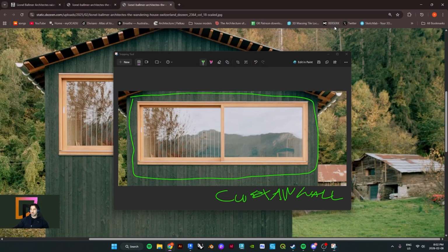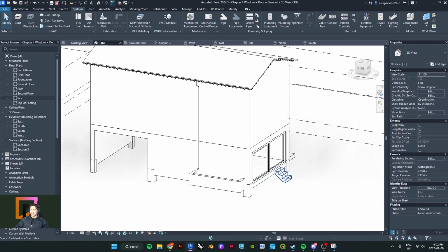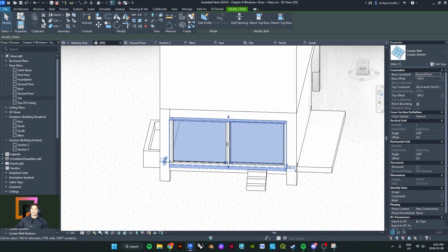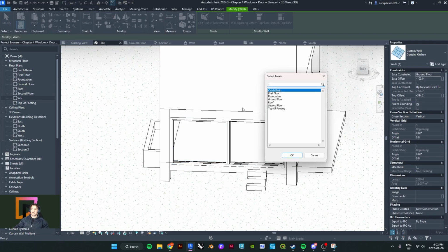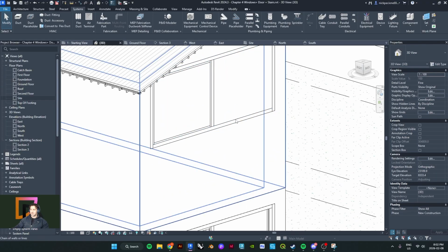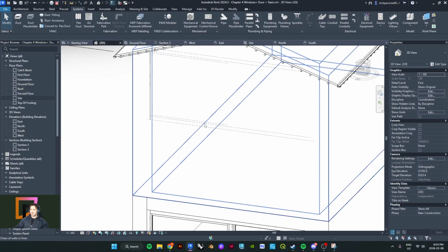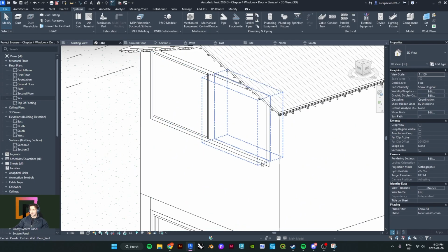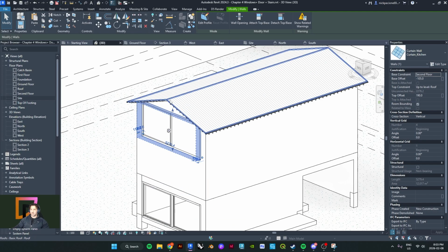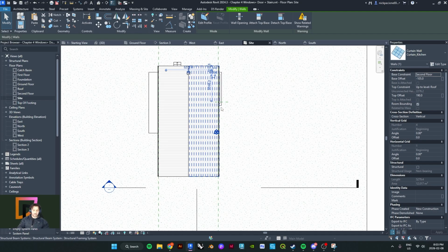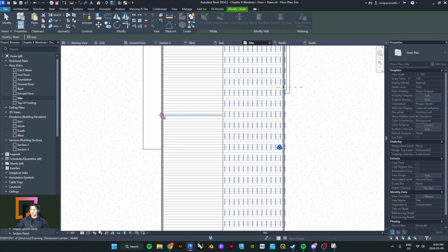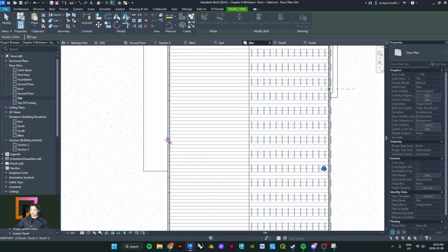Okay, so let's get started. I'm going to go back into Revit. I'm going to take the curtain wall that we made first. I'm going to go copy, paste, align to selected levels, and we're going to choose second floor. And now, let's see what's happening here. I'm going to select and grab the curtain wall. And then I'm going to come into the site plan and, if you could guess, I'm going to press DM. Mirror dimension. And I'm just going to mirror it from the middle point, from here.